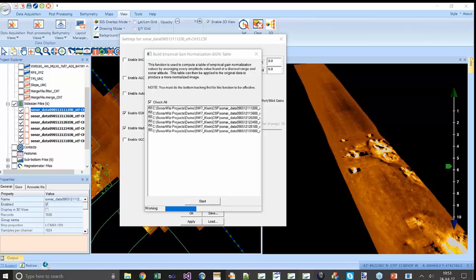We have 2 different systems right now. The vessel editor is used for bathymetry files only, and you can enter GPS offsets and other vessel information, like sheave offsets and that sort of thing, in the traditional place in SonarWiz. So it's a little confusing right now, but you currently can do that, but you do it in a different spot in the interface. At the moment it's done with the Sonar File Manager is where you put those in.